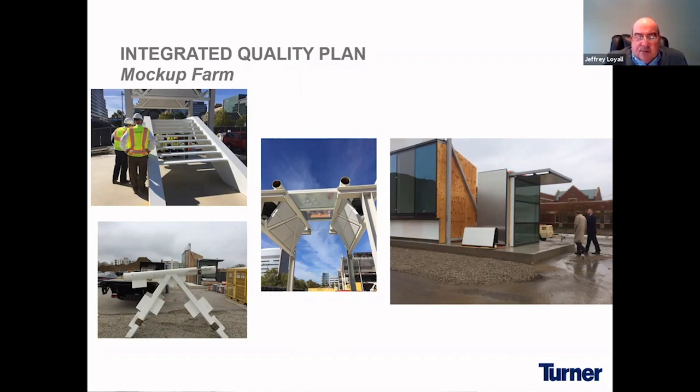One specific example was the trusses that you see in the middle. There were a lot of welds in order to put that structural steel together. The architect at one time had envisioned grinding out all the welds. So the welds are what connects the steel. And you see a piece of, if you will, putty. It's actually molten metal that hardens and is actually stronger than the steel itself. Well, the architect wanted it ground. Unground would have been a savings of $600,000.